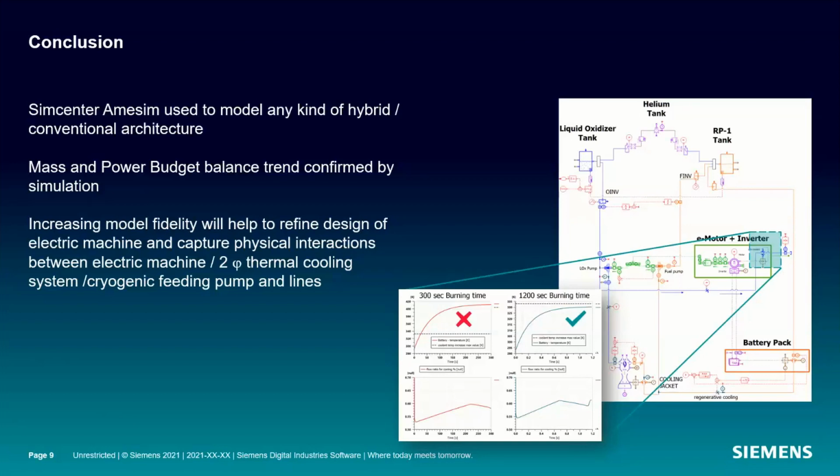We could have also had a level of better controls, right? So we might have the ability to control the required amount of flow differently through knowing the level of control algorithms. But as you see, from just the two different analyses, the one with the best mass reduction or even power budgeting would ultimately be the electric motor and inverter design versus the generator design. And that would be after the 1200 second burning time, so the full dissipation of that battery.